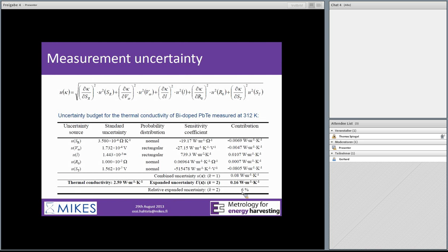We measured almost 10 different kinds of measurements throughout this project, and typically the uncertainty values were between 5% and 8%. And it seemed that those materials that have higher thermal conductivity also have higher uncertainty. One reason is that for highly conductive materials, the slope of this 3 omega voltage measurement is very flat, and it's difficult to accurately determine the slope of such a flat curve.